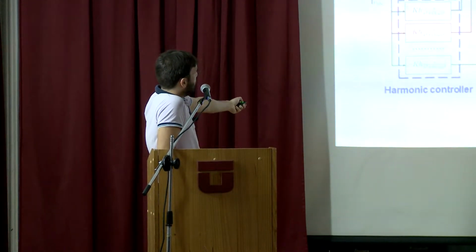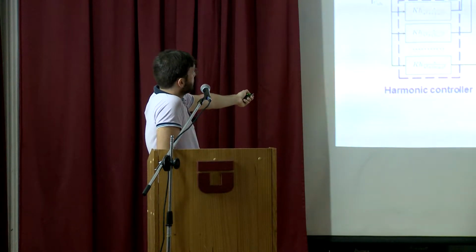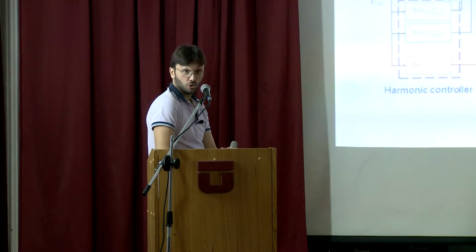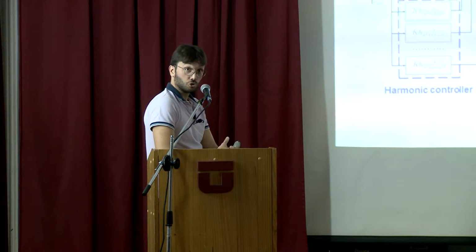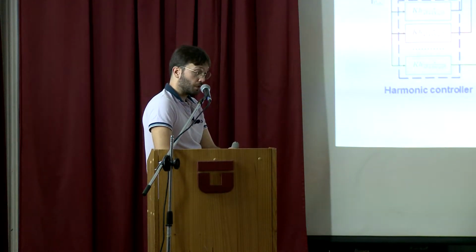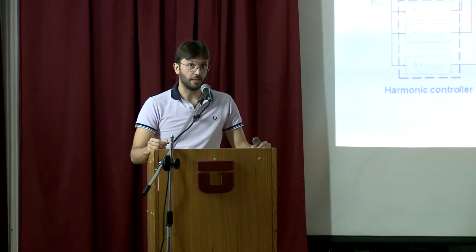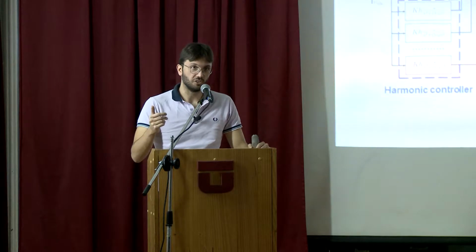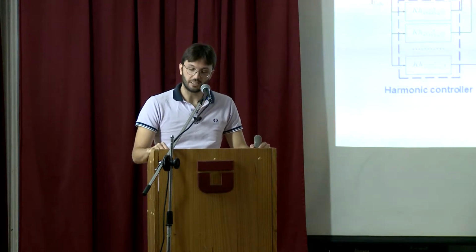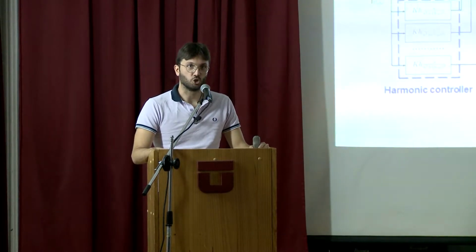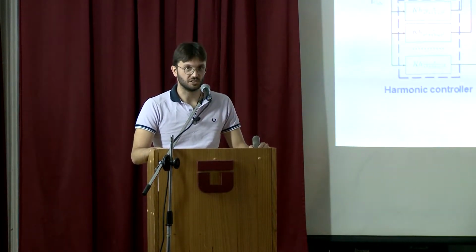And to have a nicer waveform, usually we can adopt resonant controllers, for sure one at 50 Hertz. But what we didn't see yesterday in the ideal simulation, because we had resistive loads, which are very nice, is that unfortunately the grid doesn't behave as a resistive load.